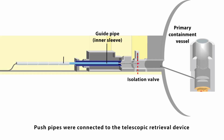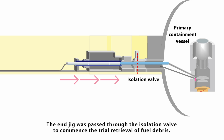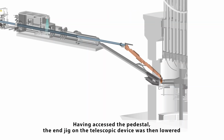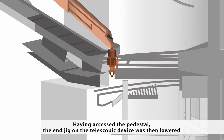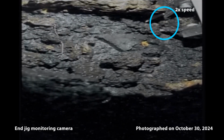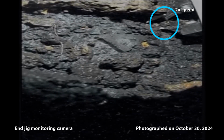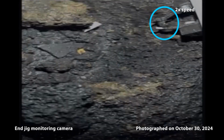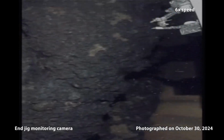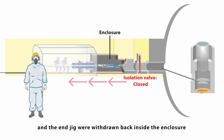Push pipes were connected to the telescopic retrieval device and inserted into the primary containment vessel. The end jig was passed through the isolation valve to commence the trial retrieval of fuel debris. Having accessed the pedestal, the end jig on the telescopic device was then lowered to grasp fuel debris. After the end jig was hoisted up, the guide pipe and the end jig were withdrawn back inside the enclosure.